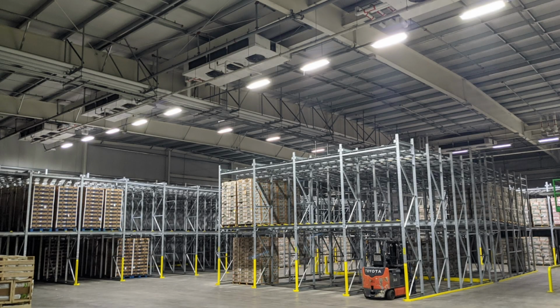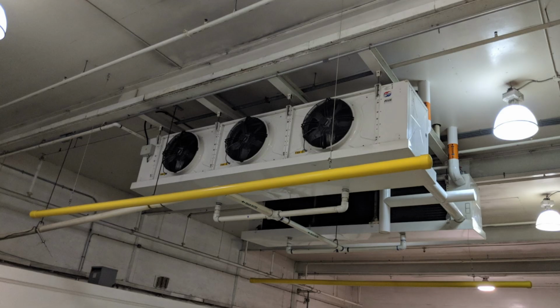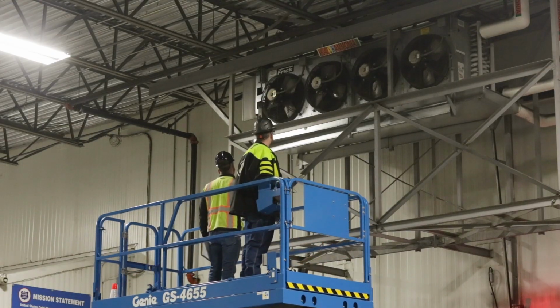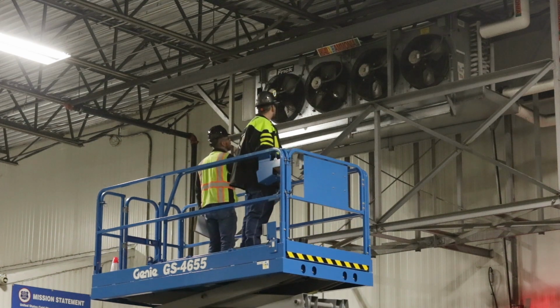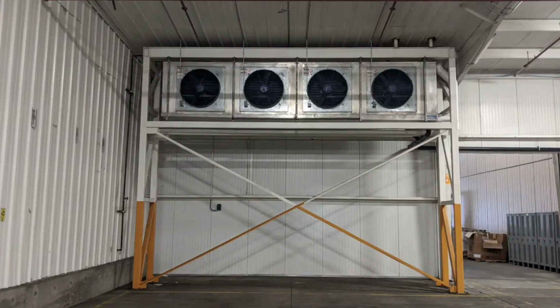Many air cooling evaporators are suspended directly from the ceiling. These ceiling suspended units are typically packaged for this purpose. It is vital to ensure that the building is designed to carry the weight of the evaporators before they are installed in this manner. A downside of ceiling suspended evaporators is that they often require special equipment, such as a scissor lift, to access them for service and maintenance. When a building is not designed to support the evaporator, a dedicated support structure anchored to the foundation can be used to support the evaporator.